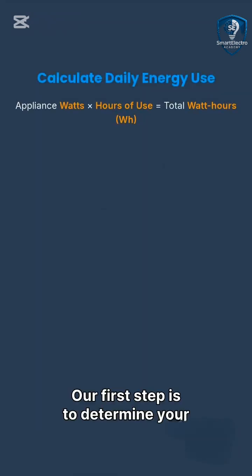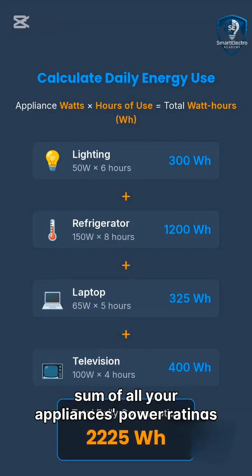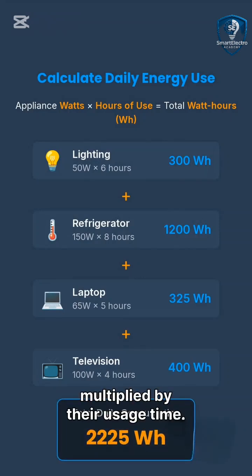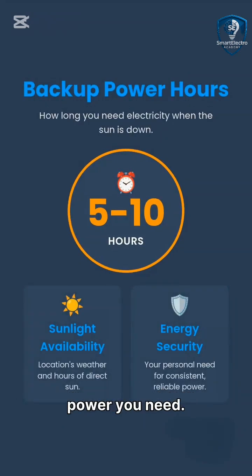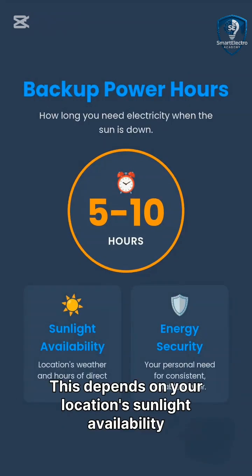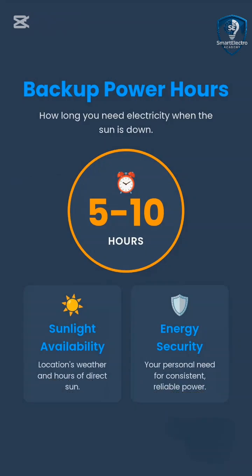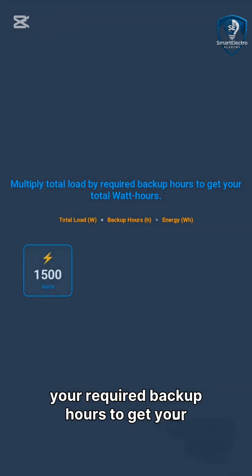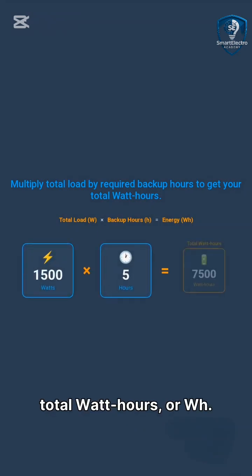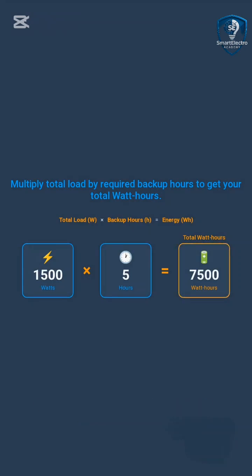Our first step is to determine your total daily energy consumption, which is the sum of all your appliances' power ratings multiplied by their usage time. Next, consider how many hours of backup power you need. This depends on your location's sunlight availability and your personal energy security preferences. Multiply your total load in watts by your required backup hours to get your total watt hours, or Wh. For example, 1,500 watts times 5 hours equals 7,500 watt hours.